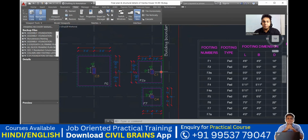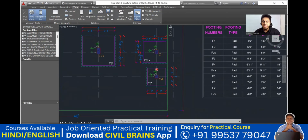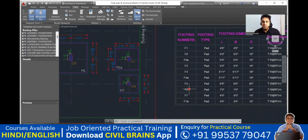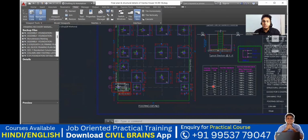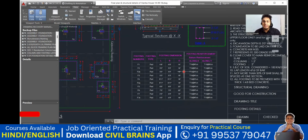Okay. For example, if I consider F6 footing, what is the size? It is 7 feet by 7 feet. Agree with me? Come here, come to the F6 footing. So this is my F6 footing. So what is mentioned here? 7 feet by 7 feet. But this 22 inches, you don't get it here. It will be written in the cross section part. So that is why they have made a separate table for this and they have given it here.